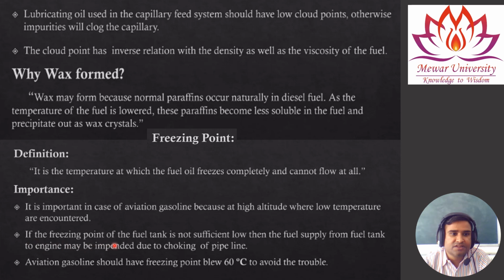If the freezing point of the fuel is not sufficiently low, then the fuel supply from the fuel tank to the engine may be impeded due to choking of the pipeline. Aviation gasoline should have a freezing point below minus 60 degrees centigrade to avoid these troubles. So this is the importance of the freezing point. It should be as low as possible.